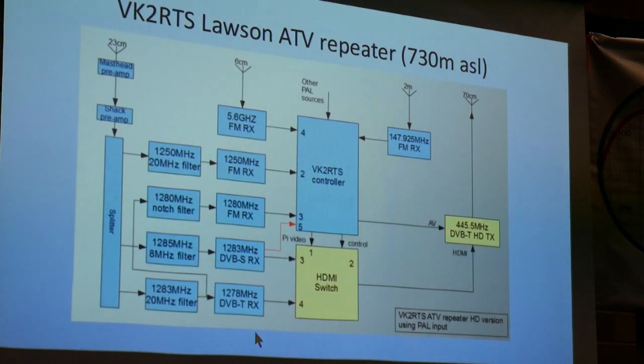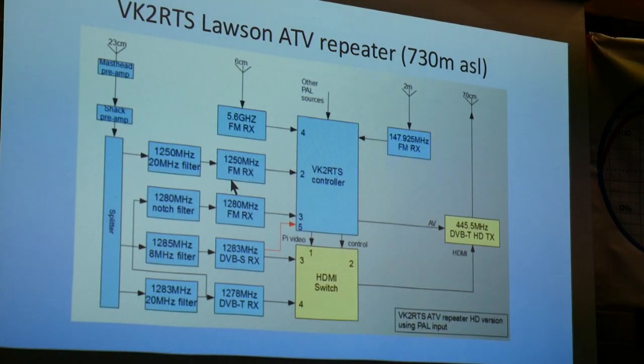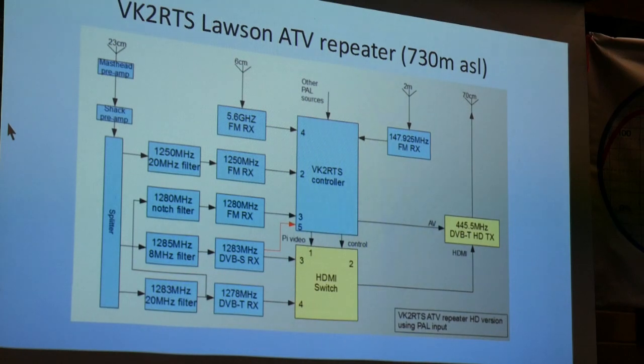into those receivers. So the dishes use something like 1296 as a downlink frequency, do they? Yeah. Oh, very convenient. Perfect. Very convenient. Yeah, covers the 23 cm amateur band with no modifications. So that set-top box there is receiving that transmitter over there with this little bit of wire just stuck out the back of it. And it doesn't have a dish and an LNB on it? No, nothing. So it's the easy way to receive. I'll show you this later.